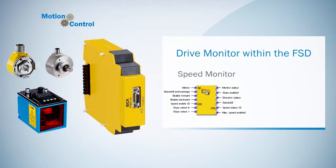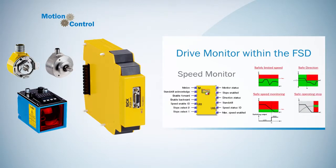Moreover, there are also the outputs speed status ID and max speed enabled. Speed status ID outputs the current speed range of the drive. And the output max speed enabled is high if the highest speed range is activated by the input speed enable ID. With the add of these in and outputs, plus the appropriate configuration, this function block can perform the functions safely limited speed, safe speed monitoring, safe direction, and safe operating stop.